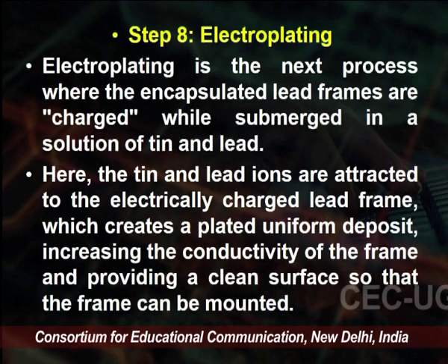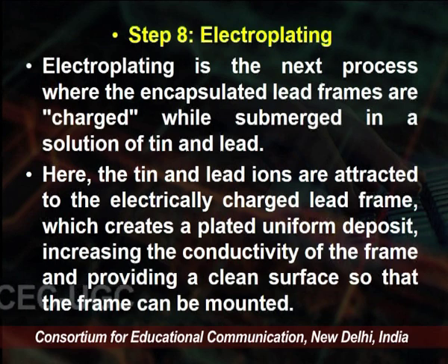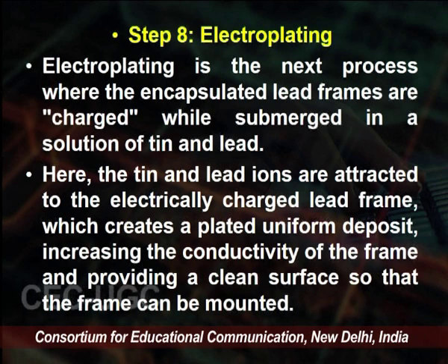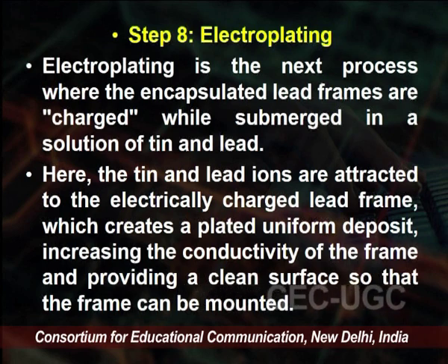Another step is electroplating. Electroplating is the next step after encapsulation, where the encapsulated lead frames are charged while submerged in a solution of tin and lead.